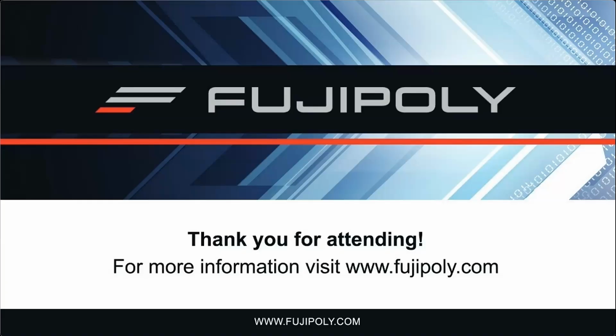And then if you have no gap, if it's basic metal to metal contact, thermal grease, we do have a couple, I think 2 or 3 different options that are non-silicone as well. Next question is, what is the highest thermal conductivity for these materials? So for thermal greases, we go up to 6 watts per meter Kelvin, and then for the dispensable gap fillers, we go as high as 7 watts per meter Kelvin.